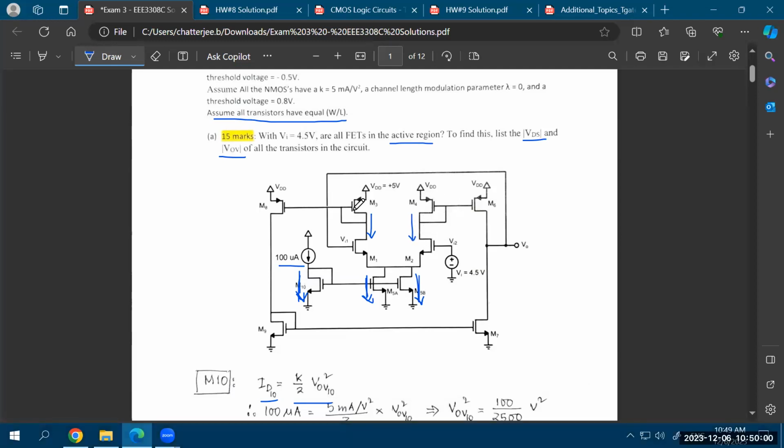Now look at these top PMOS transistors. They are diode connected. So this is the drain terminal of the PMOS. This is the gate terminal of the PMOS. So this is diode connected, and the gates of these two transistors, for example M4 and M6, are connected together. So again, this forms a current mirror, right? On the left side, this forms the current mirror. Because of that, you'll see the exact same amount of current flowing in the two branches of the differential amplifier. So those are 100 microamperes, but also the current flowing in this and the current flowing in this is also 100 microampere.